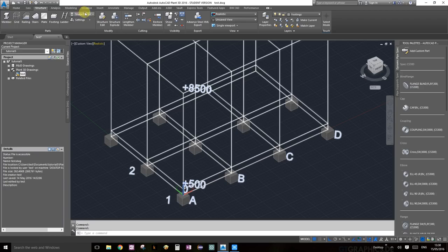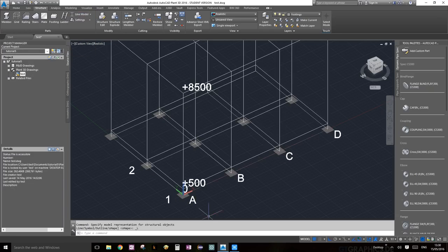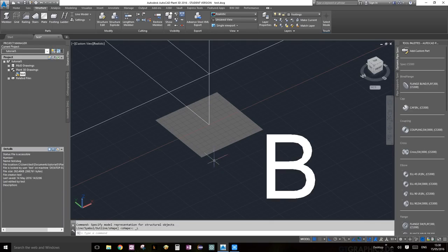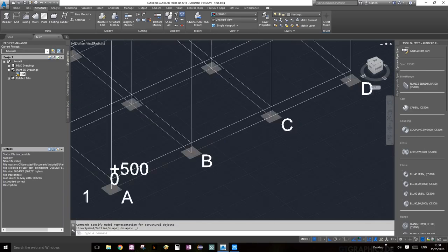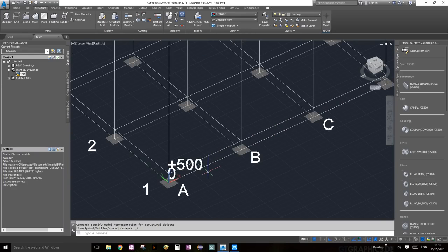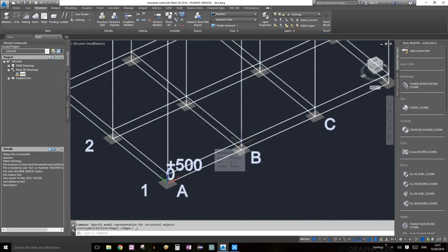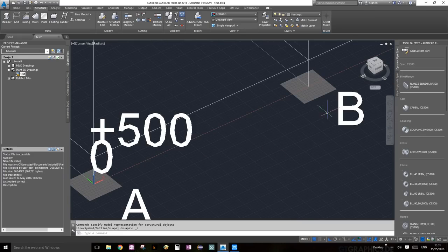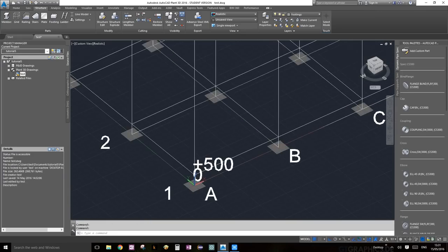If you go on the structure palette again and on the parts section, there's a little drop down box here that says shape mode. It's on shape mode. If you go on line mode, it will only show a cross-sectional representation of your footing or any structural member, really. One huge advantage of that is, if it's not the actual 3D representation, then you're able to select all the points, all the nodes easily.